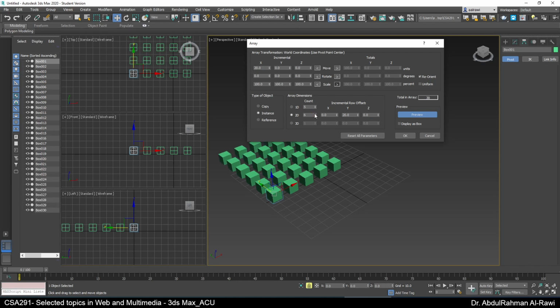Okay, imagine there are buildings and you want to create buildings, and these are all objects. Now if the scene is very complex, or if the model that you are making array of is complex, not like a very simple box, like a fish or like a dinosaur, you can check this on to display them as boxes, and they're going to be displayed as bounding boxes just to, let's say, save your memory resources and make the view much faster. But there is no need for this now.